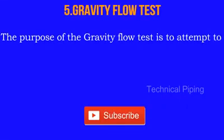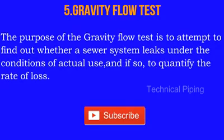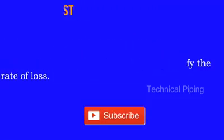Number 5. Gravity flow test. The purpose of the gravity flow test is to attempt to find out whether a sewer system leaks under the conditions of actual use, and if so, to quantify the rate of loss. This test is also called the water fill and flow test.